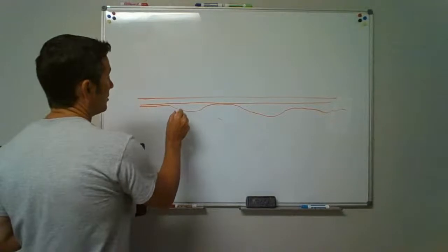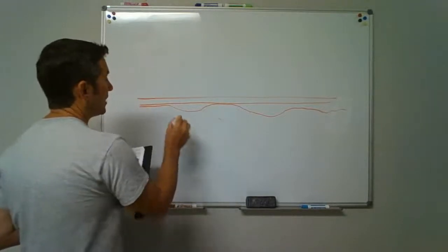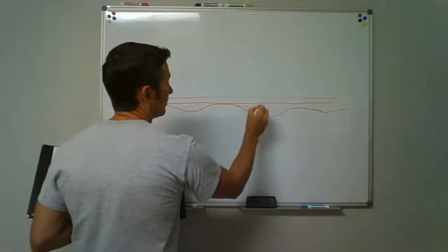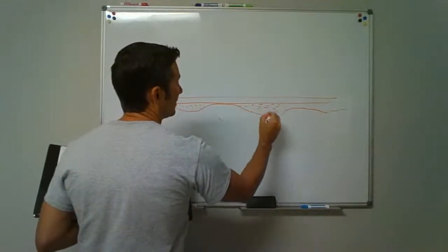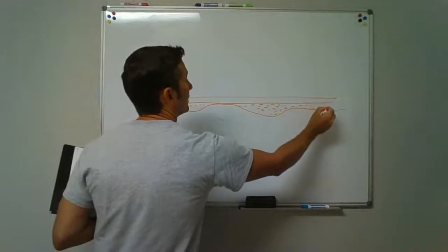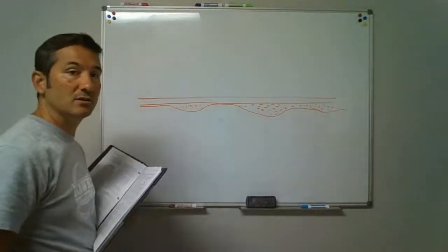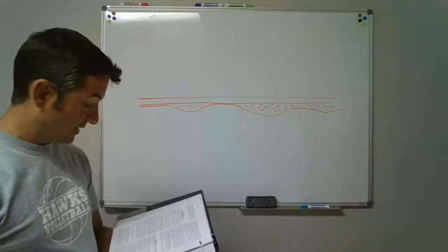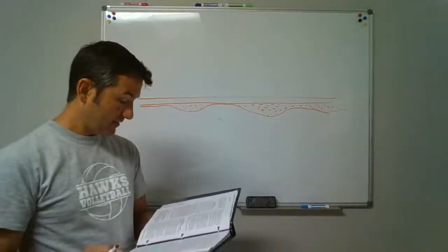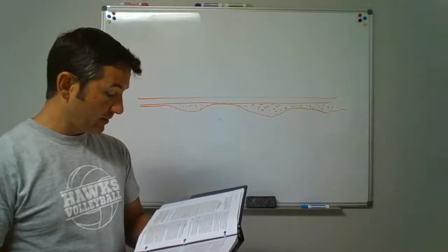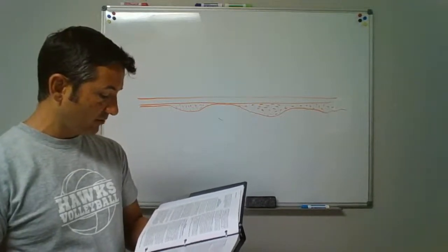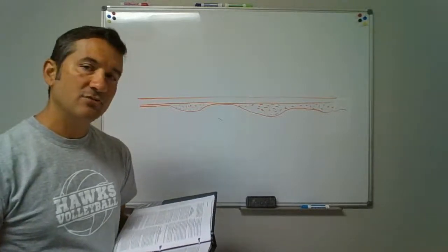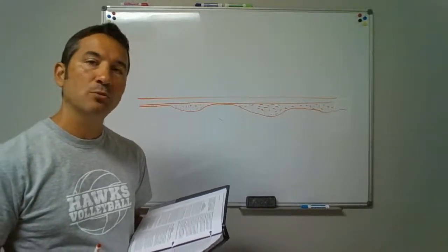So we don't want to also just say, oh, well, don't worry, I'll just shovel a little bit of loose dirt into those areas. There we go, I've got them filled up now. Nice loose dirt, because that loose dirt's going to settle out as well. So if you over excavated, 306.2 says the trench shall be backfilled to the installation level of the bottom of the pipe with sand or fine gravel. You can't even shove the dirt back into the ditch that you put in there before.